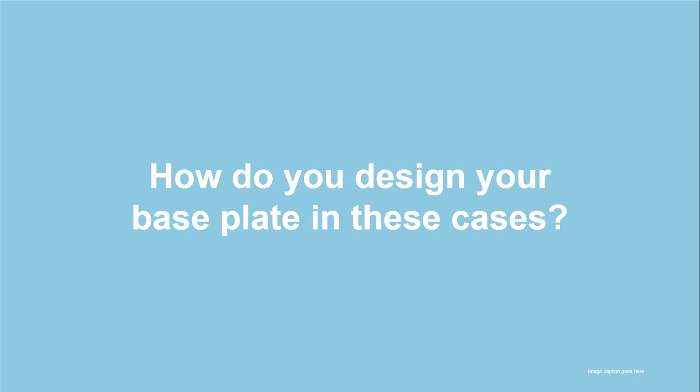Exactly. And that's, again, one of the things we are currently working on, in order to allow you to put stiffeners as well. Because as we saw, if my profile has a stiffener, this will stiffen the base plate and my load distribution will change dramatically. Let's just assume I put a stiffener here until here. I can tell you that the center of compression will probably move almost to the edge of the stiffener, and from a lever arm perspective, you have probably gained 20, 30, whatever percent, right? That's a very good point.